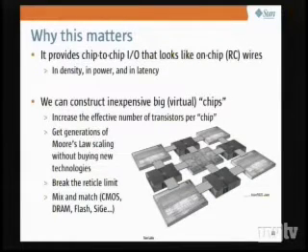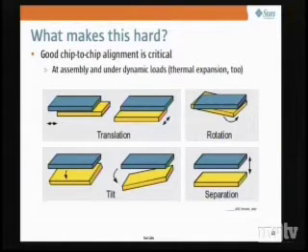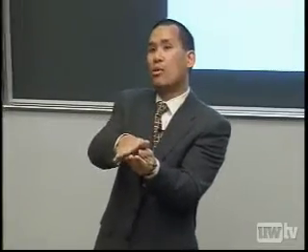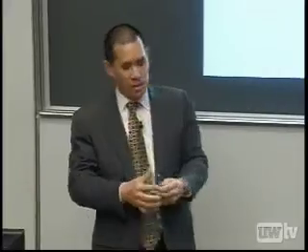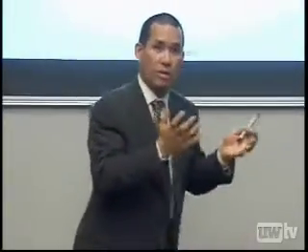All right, well, that's an appealing story, but there's always a cost, right? What's hard about this? And what's hard about this is alignment. So I've got these pads on these two chips, right? Now, if the pads are aligned perfectly, I can communicate, but what if one chip gets hot, expands, or contracts from thermal differences? What if somebody walks by the computer system and sort of jumps and the whole thing shakes? What if you sneeze when you're next to the chassis?